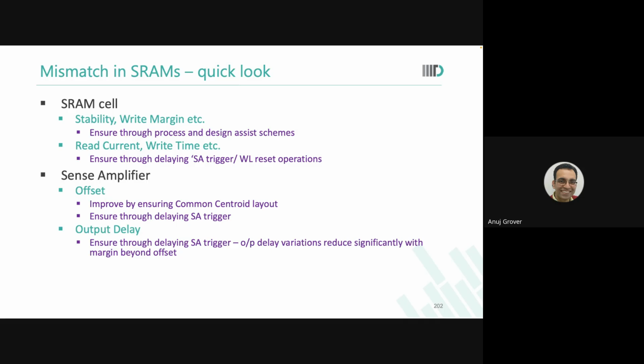So all that has to be done through statistical verification. You cannot simply bring me one result and say, sir, this is my offset. I will say, okay, what is the sigma? And you will say, sir, मैंने तो single simulation चलाया है. सीधा zero. Are you getting it? So at circuit level itself, we are already saying that we have to take care of qualification of these circuits at plus minus 6 sigma or 4.5 sigma, depending on how many times that circuit is expected to be repeated in your designs.